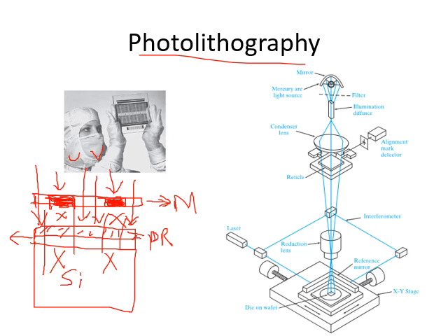Depending on which photoresist we have used, positive or negative, the exposed part can be etched away or it becomes weaker. This shaded part can become weaker or soluble. Or the other way can happen: this part may remain as it is, but the part which is not exposed to UV radiation can become soluble.